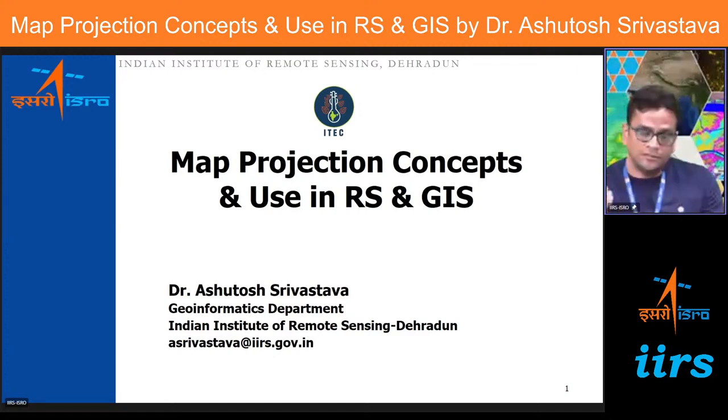But if this information is not in digital form, you have to digitize it first. When this information comes from different sources, they may have different coordinate systems or projection systems. So first, we have to make a common coordinate system or projection system for all the layers.